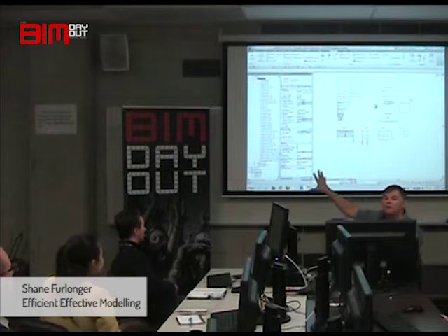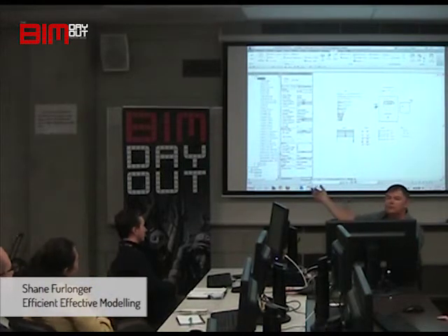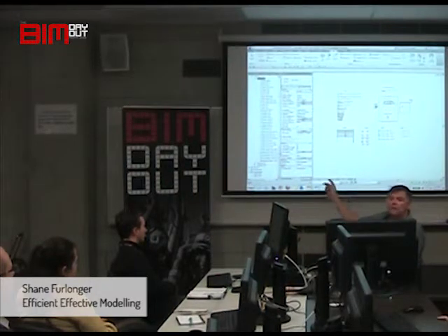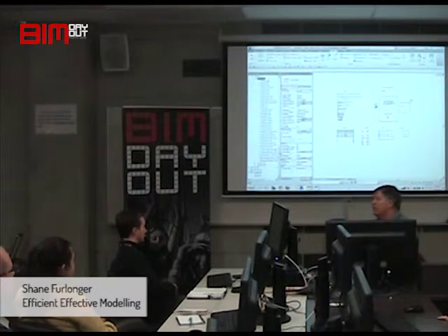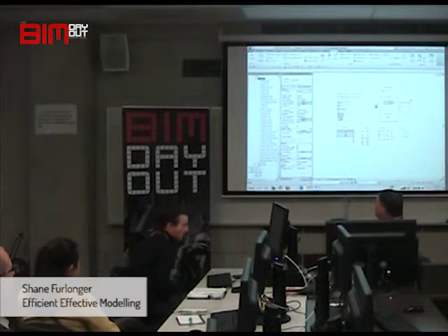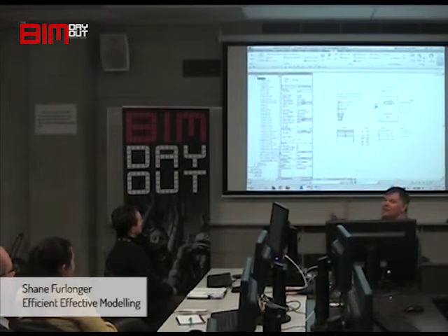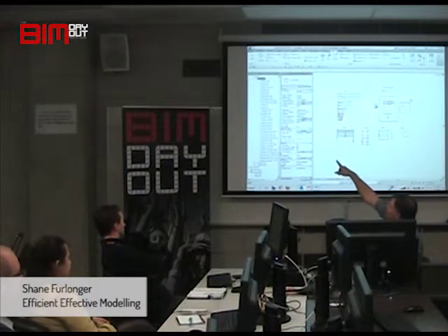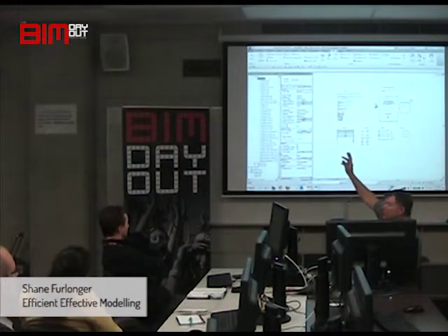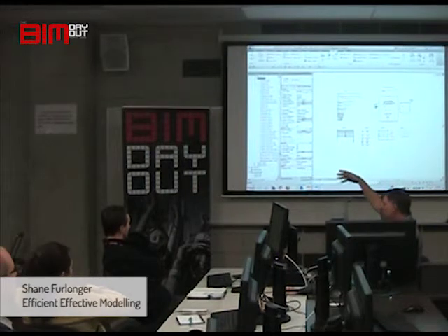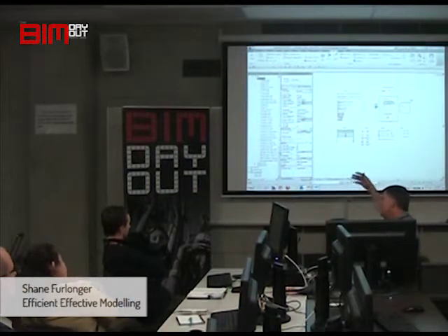So your stuff is always grouped, and if you're importing things or opening other people's files and you want to bring in your families, then if you've got a number in front that's you or your company, it's all grouped together and you can find it easily. But the other thing is, name it so that you understand what it is. Because I've opened files where it says HSL underscore blah blah blah underscore blah blah blah MB3.